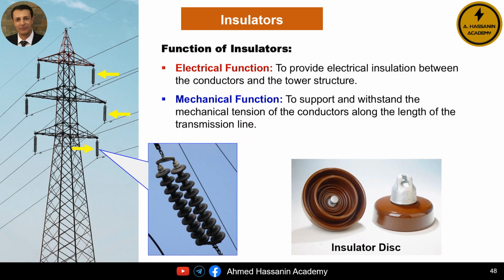Second, a mechanical function, which is to support and hold the conductors or the wires or the phases in general along the length of the transmission line. The second important point we need to understand is that the insulators used in overhead transmission lines consist of a set of discs, and of course, these discs are assembled and arranged together to form what is known as the insulator string, as clearly shown in the image.